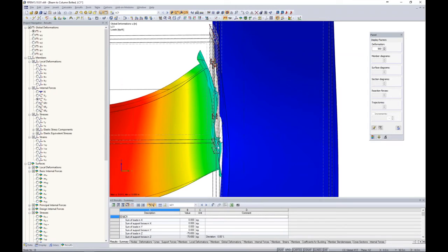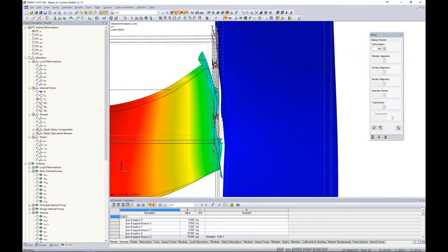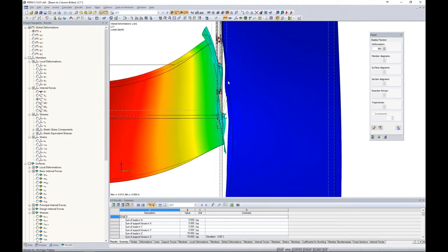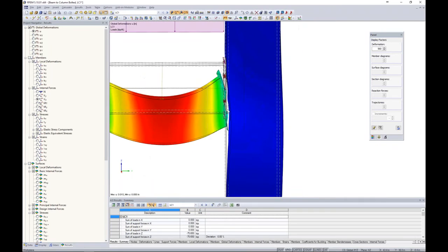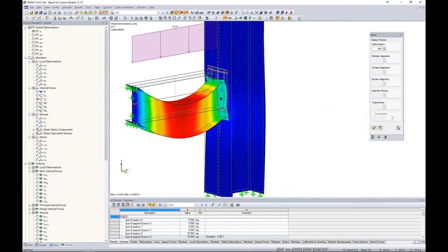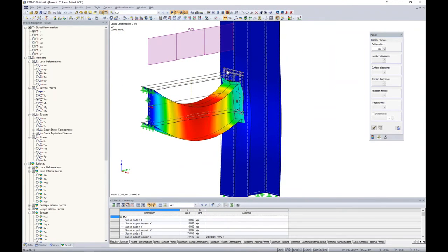As we move along the plate, in places where there are compression forces, that's where we should see the full interaction between the 2 surface elements, or actually multiple surface elements for these contact solids now. Here are my bolts in tension, of course, as well. So same exact concept. The only thing that I did was split that contact solid into several simpler elements.